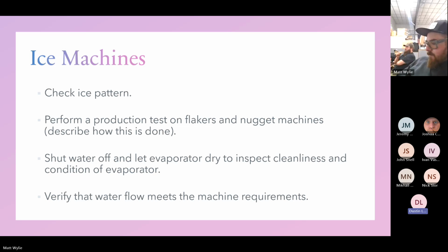Yeah, I know a lot of us have all been there. We've all had a bad valve and we reach out to Parts Town or whatever to try to order the OEM. But it's usually going to be a Sporlan valve or a Danfoss valve. And if it's a Sporlan valve, you're going to be able to find the body type and the power head type. You're going to find everything you need at the supply house. That's a lot better than paying double the price and waiting 4 weeks for an expansion valve that either the parts house can make or you can make yourself.